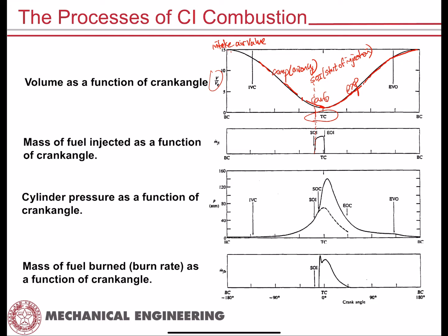And then that fuel injection process is when you are injecting fuel at a very high pressure, at least an order of magnitude, and mostly nowadays two orders of magnitude, higher than the air pressure inside the cylinder. So you're injecting this fuel directly into the cylinder during a period of time. And when that injection is over, you then have what is called EOI, which of course is end of injection.